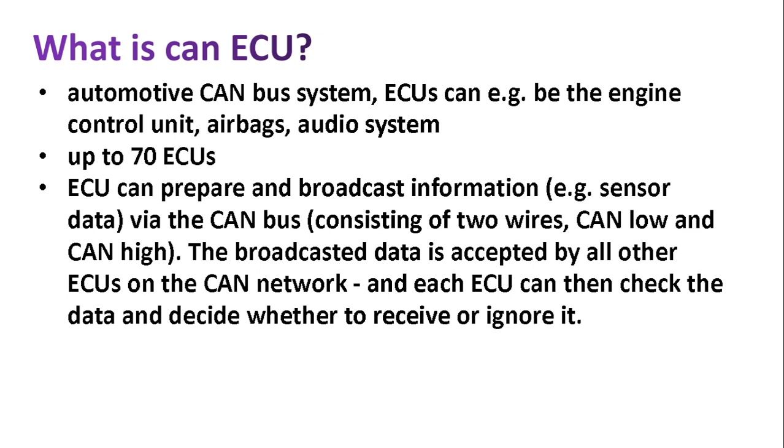Okay, so if I want to open the door's glass, I press the button. So what signal is sent from the ECU? Open the door glass, right? So the ECU will create one signal and pass it throughout the cable, right? Just assume 111 is the signal which the ECU passes, and the 111 signal is assigned only to the door glass opening unit.